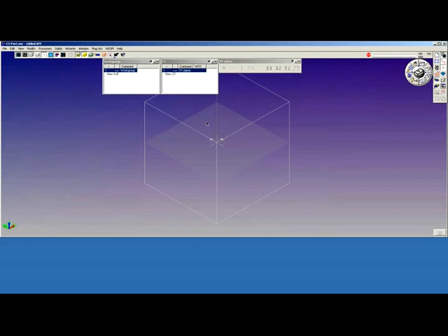In defining coordinate systems or a four-axis environment, the default coordinate system cannot be modified. As you can see, when I click on the coordinate system palette, none of the tiles activate. It's all grayed out. This is because we're dealing with the default coordinate system. The default coordinate system cannot be modified, moved, or toggled for depth.